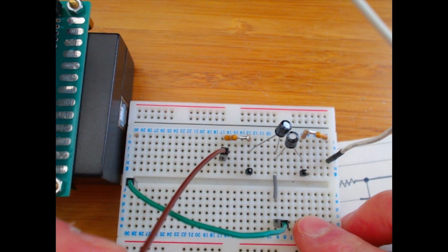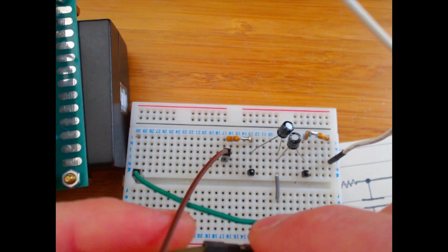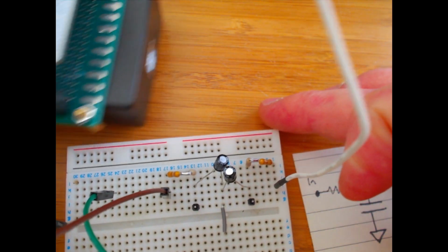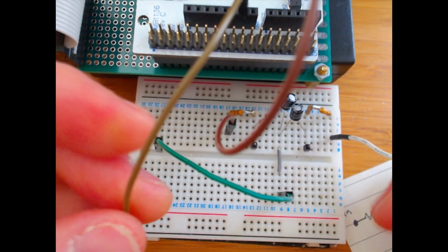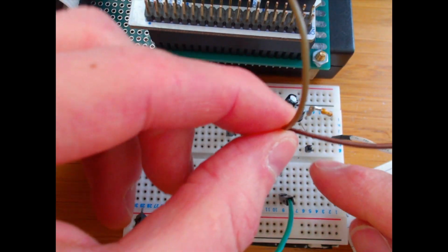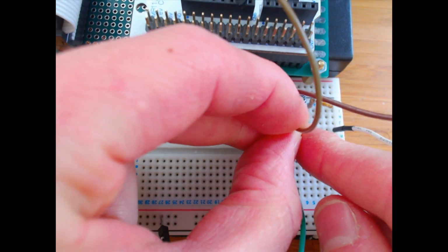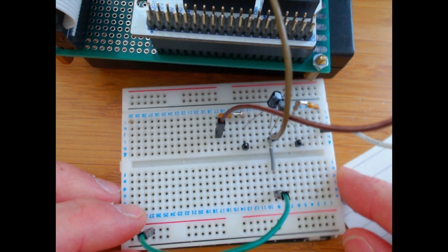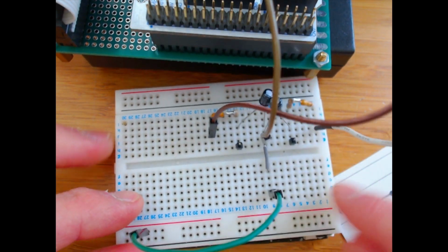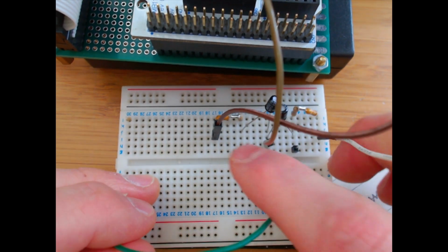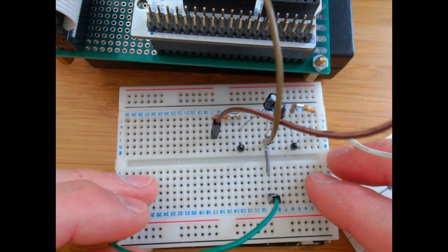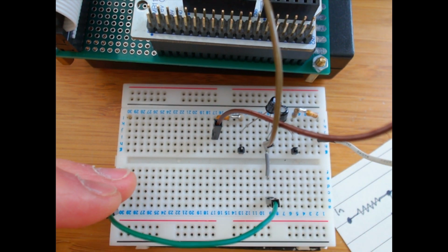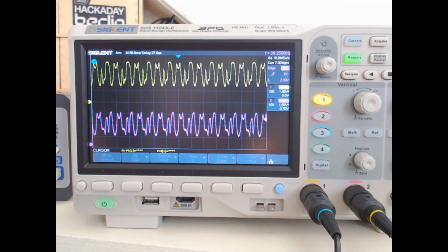And then we need a ground point. So this is ground, and what I will do is take this ground wire and plug it in between these two capacitors there. So that's the final filter, and now we can just clip onto this and view these 2 points here with the scope, and hopefully that will work. So let's get that set up. And this is what it looks like on the scope. So yeah, that actually looks like that's worked really well.